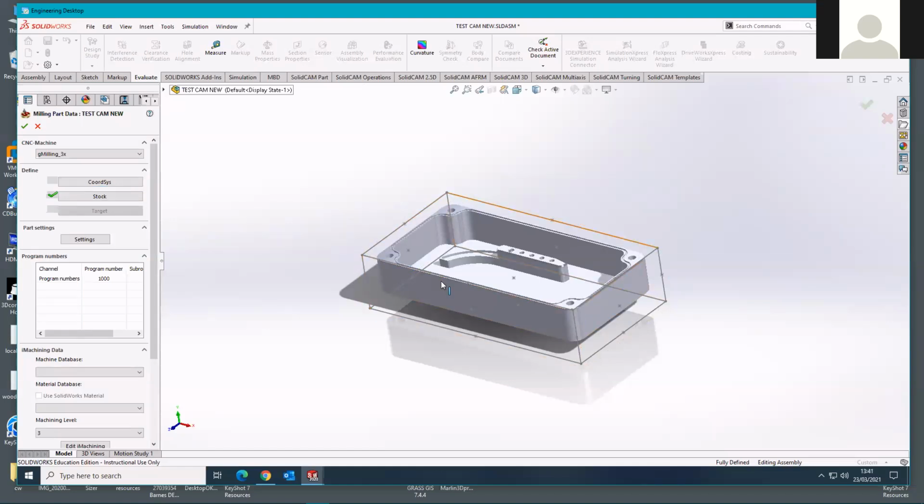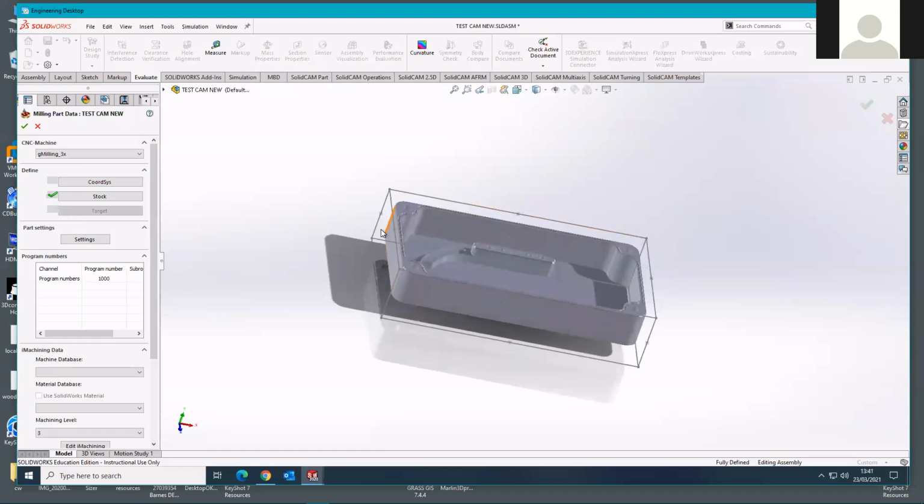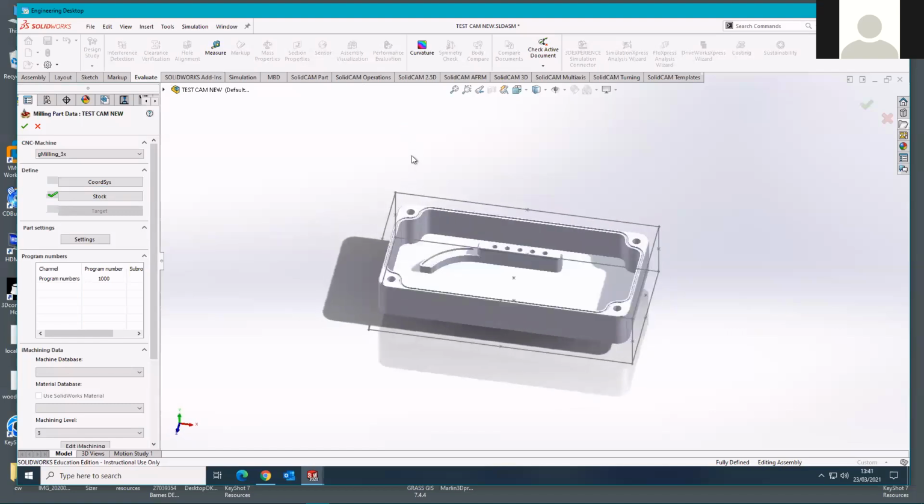You put the stock material in, clamp it down, and then you can use the CNC head itself to actually clock or measure where each face of that stock material is. So you can tell the CNC machine our coordinate system, for example, is sat at this back left corner of our stock block. So that's what we're going to do next.